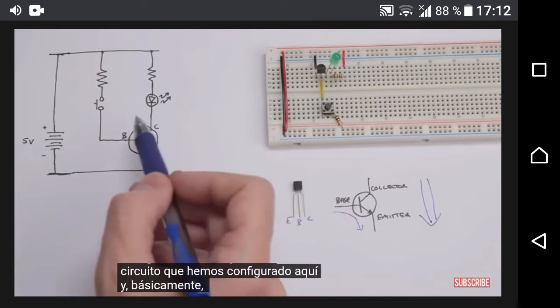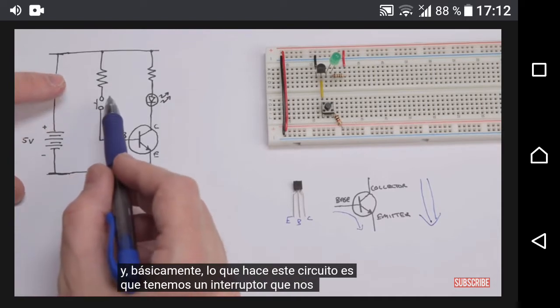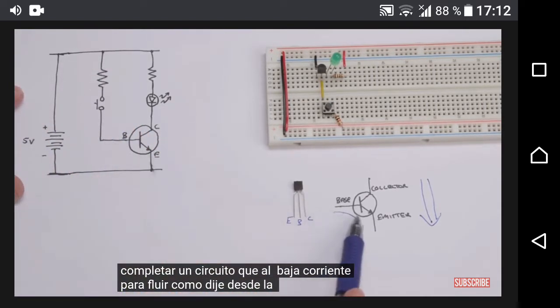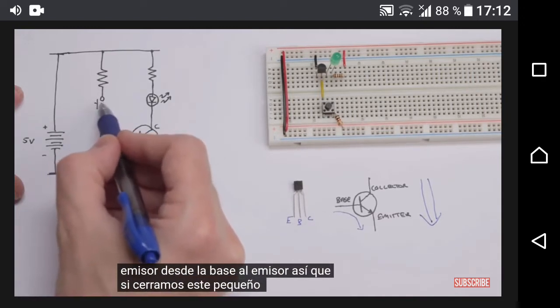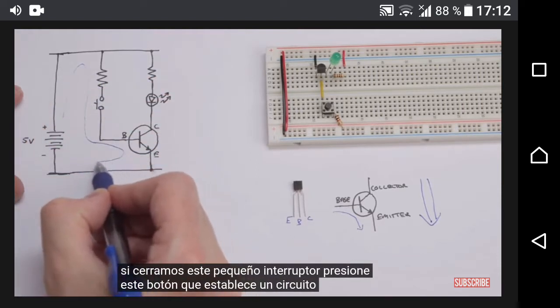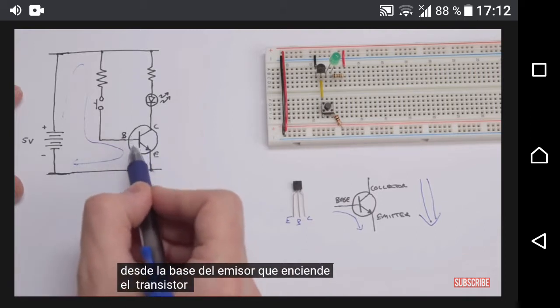Basically what this circuit does is we've got a switch that allows us to complete a circuit that allows current to flow, like I said, from the base to the emitter. So if we close this little switch, push this button, that establishes a circuit like this and causes current to flow from the base to the emitter. That turns the transistor on.